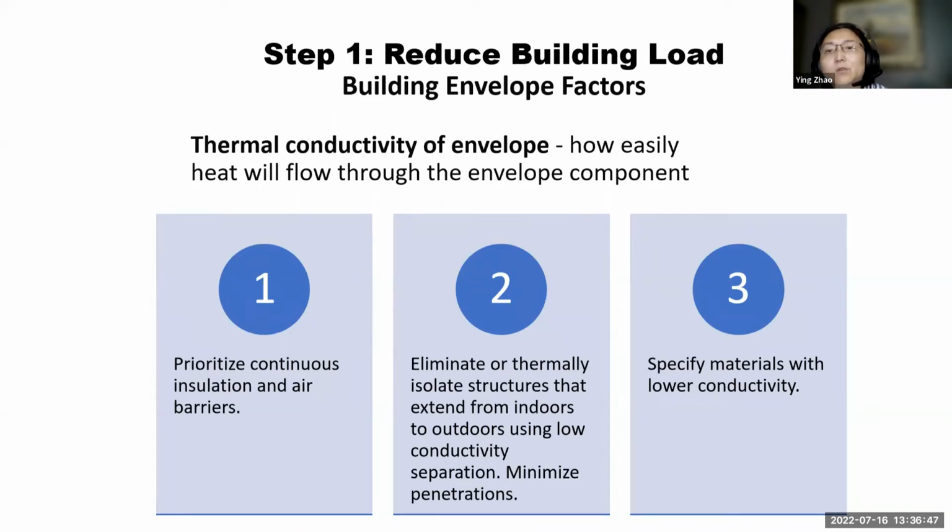And the third design consideration will be to specify materials with lower conductivity, to reduce the U value of the building envelope.